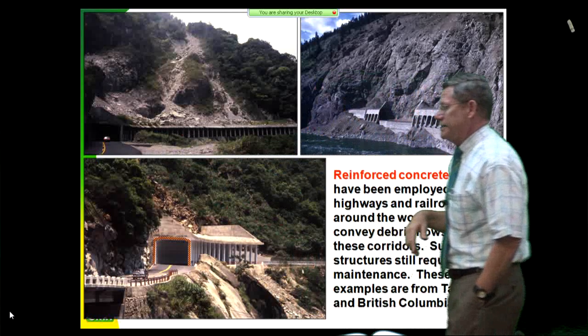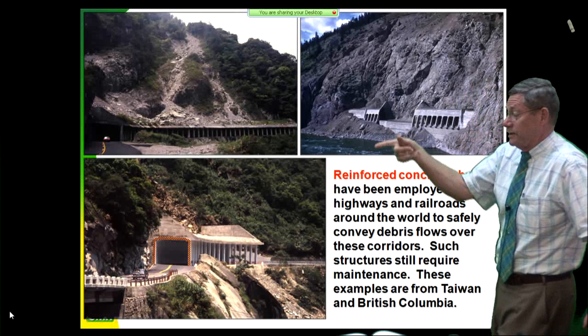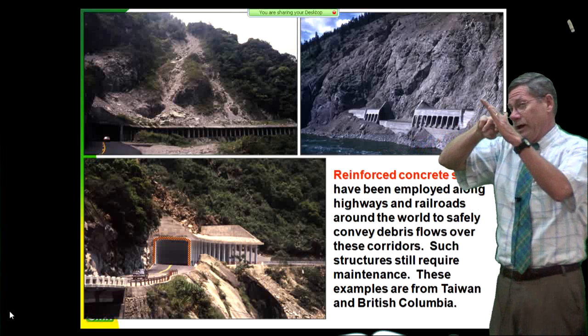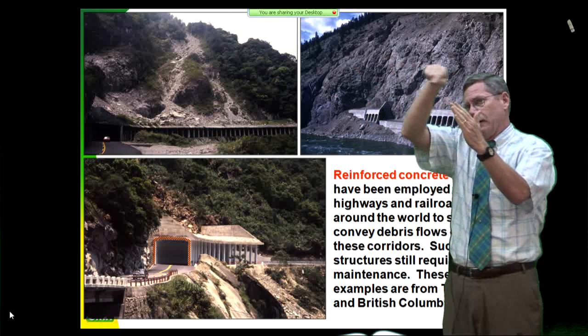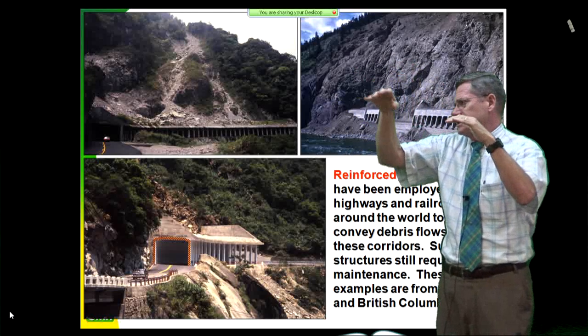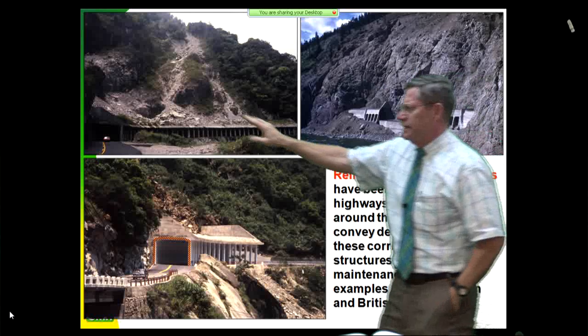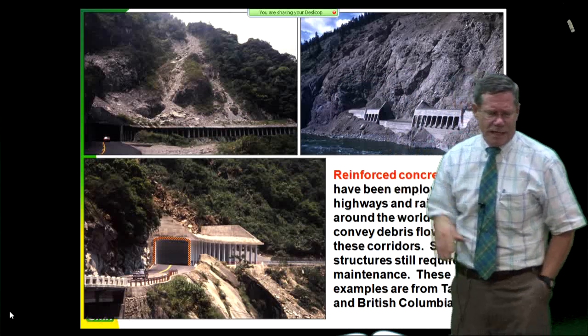Now for the Taiwanese, after the 99 quake, I actually designed a system for them that's much less expensive using parabolic-shaped culverts, where you cut out the downhill side and you split the road into two-lane sections and build them in culverts and then put the talus over them for your cushion, a rock cushion.